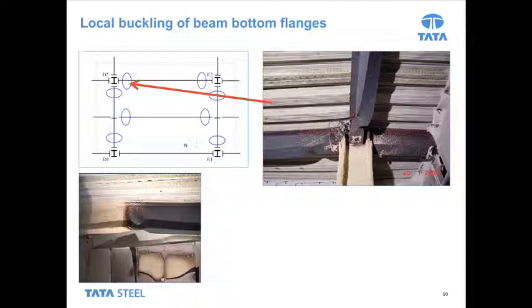Again, just taking a look at some of the photographs from the fire. What we're seeing here is a little bit of bottom flange buckling. During the fire, the steel would expand, and wherever the steel was restrained, there would have been some buckling taking place. Bottom left here, we see there was a compartment which has been removed afterwards. Steel had been protected to the left of that compartment, but within the compartment where the fire took place, no fire protection to the steel, so we've got a little bit of buckling taking place on the bottom flange due to expansion during the fire.